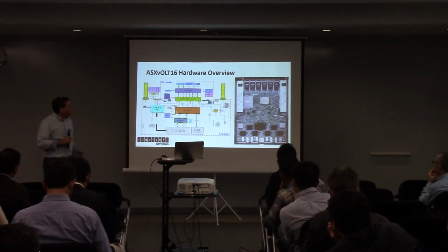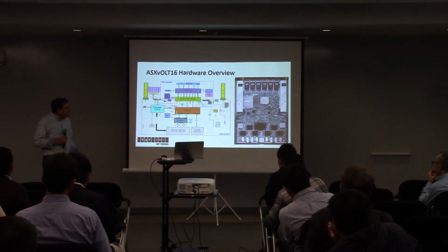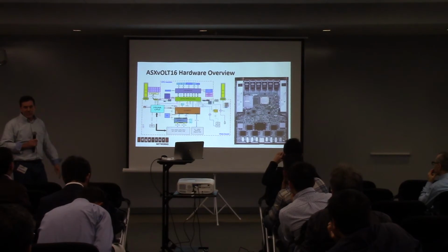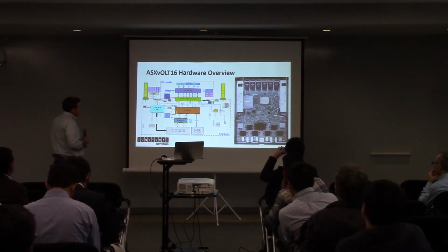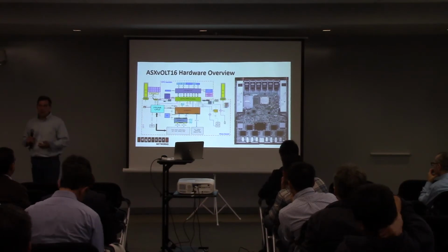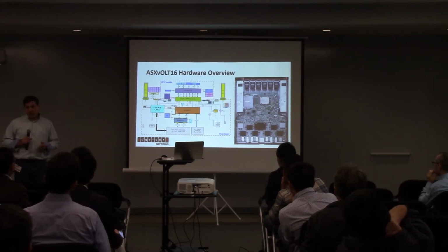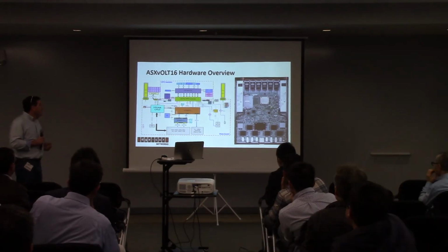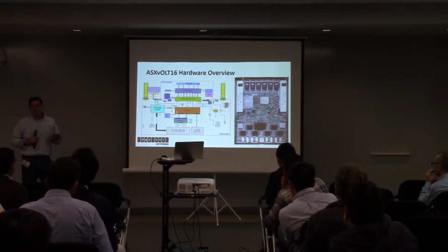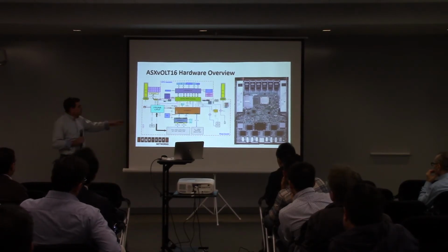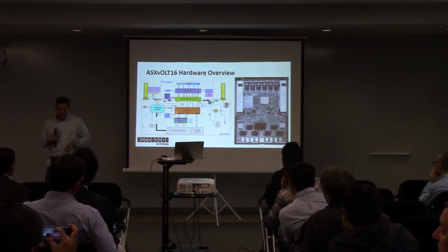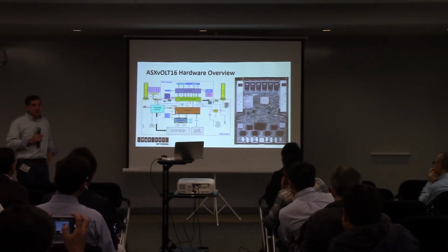As for what the hardware looks like inside, there are a few key components, and usually the key components in these types of designs have heat sinks on them, so you can't really see what they are. This design is based on a Broadcom switching chip, the Qumran AX silicon. That does all the switching functionality between and for the PON Mac chips in front. In front of the switching silicon, you have Broadcom codename Maple GPON Mac chips.